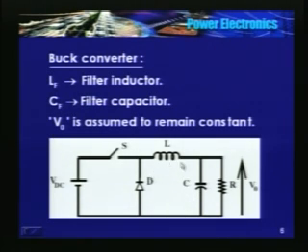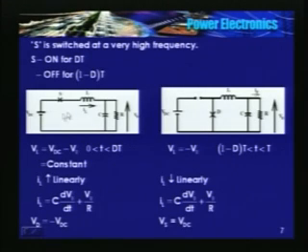The equivalent circuit is: the VDC source which is short circuited, and the remaining part of the buck converter. After some time I opened S, there is an open circuit across the DC bus here, and the diode. This is the equivalent circuit.